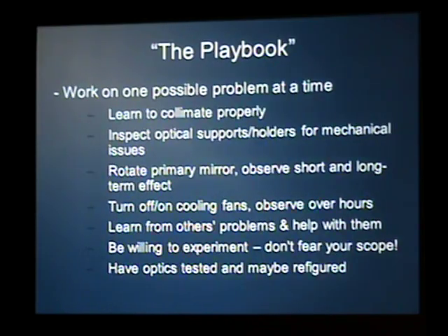We can turn on or off our cooling fans if we have them and observe this effect over hours, because often fans will set up a cooling or a temperature gradient in the mirror, and that can take an hour or two to actually redistribute itself. If you've got a cold spot and a warm spot, those have to exchange heat until the mirror reaches equilibrium. So things may not instantly go away.